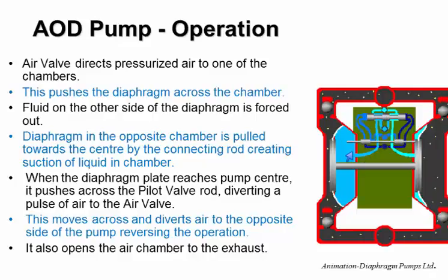That moves the shuttle back and forth, and the shuttle guides the compressed air to either side of the system. So in this case here, the shuttle has guided compressed air to behind this piston. This piston has moved to the left, and we've discharged fluid out through the discharge port there.